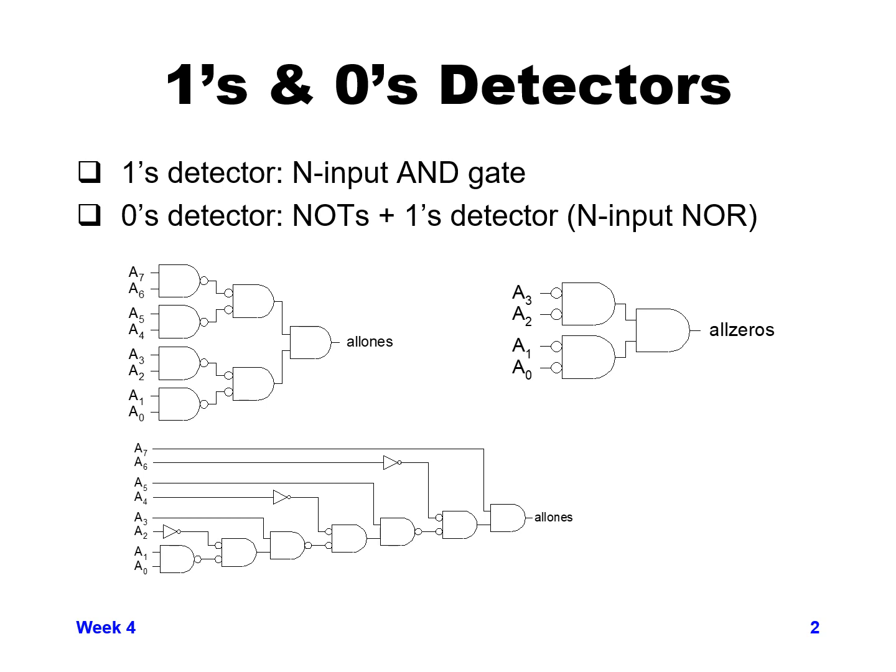Here's a couple ways that we could do circuits that actually do either our ones detector or 0 detector. For a ones detector, if you're trying to determine whether you have all ones, effectively that's an AND function. So here we've shown in the upper left, if we had an 8-bit ones detector, we're basically doing an 8-bit AND function.